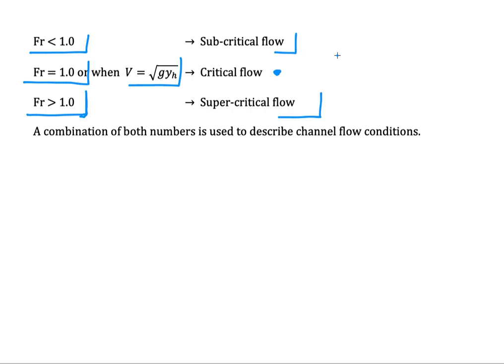So what are subcritical, critical, and supercritical? They are actually the indicator of the hydraulic jump. As I said previously, in a dam construction and so on, we are afraid that every time we release the water, a hydraulic jump will occur, because it will lead to catastrophic failure, a big failure there. So we must make sure that the energy of the water is not exceeding. How to know that is by looking at the Froude number.